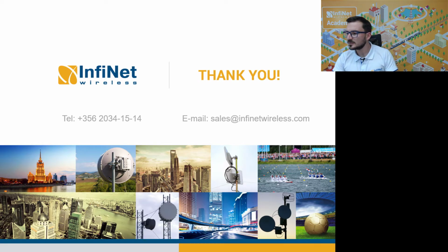Different base stations can't be synchronized if they have same couple of frequencies. They can be synchronized, of course, but I have to ask you, you mean different sites or different units on the same site? Different sites. Okay, so if we are talking about different sites, you must have at least one synchronization device at each site.